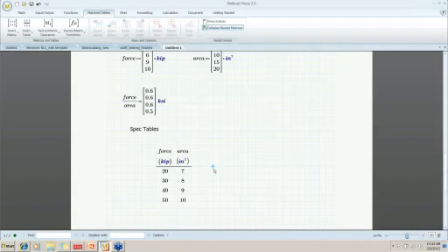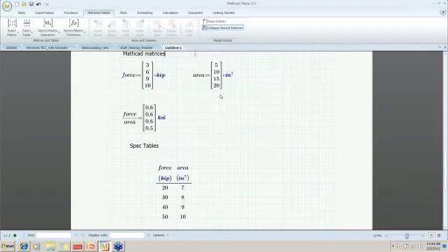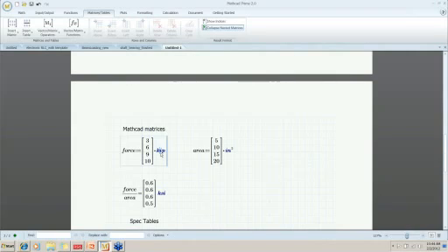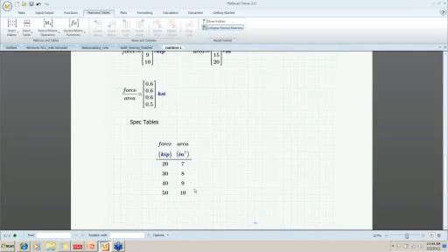But you have the look that you would have in a spreadsheet. A lot of people like to do this versus doing it this method up here, creating a force variable and then creating it as a vector and then assigning the inches at the end, like we did here. A lot of times you might prefer more of a table representation of your data. Now if we type force equals to display the force variable, you'll see that it contains this column data in units of force. Newtons is the default for SI. Remember, I'm in SI, but we could convert that to kips and then we'll see the replica of the way we entered in the data.